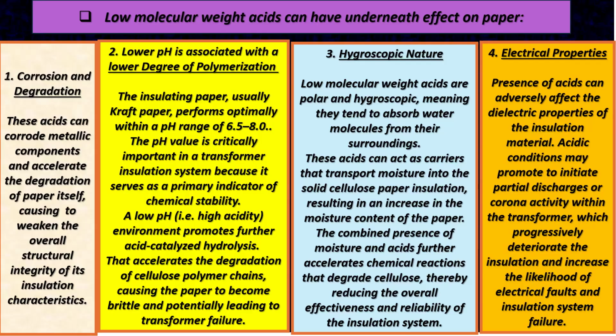Electrical properties. The presence of acids can adversely affect the dielectric properties of the insulation material. Acidic conditions may promote and initiate partial discharges or corona activity within the transformer, which progressively deteriorate the insulation and increase the likelihood of electrical faults and insulation system failure.